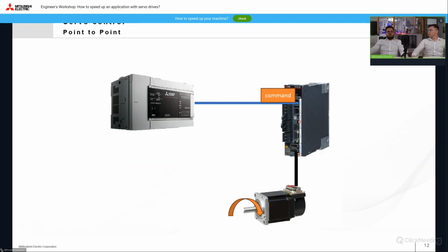Point-to-point control works on the principle of sending a movement command and waiting for a signal indicating that the position has been completed. All control of the motion loop is done on the amplifier side, although we have feedback from the drive about the current position, status, etc. This is subject to an error due to the timing of the communication cycle. In other words, it is information at the time of sending, not the actual current status of the drive at the moment.